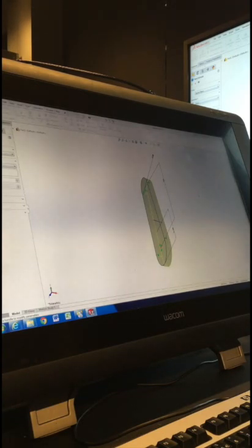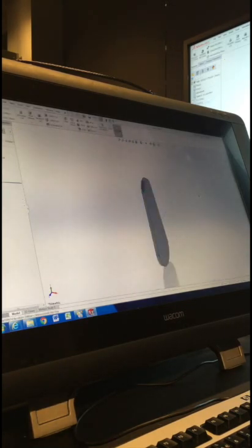All right, so that's your preview. You can adjust the thickness. Put in whatever thickness you think it should be. Have a look at the drawing. It doesn't really matter. Remember, we're going to come back and change it anyway. I'm going to put in 5 and press OK or press Enter again. That's created Boss Extrude 1.